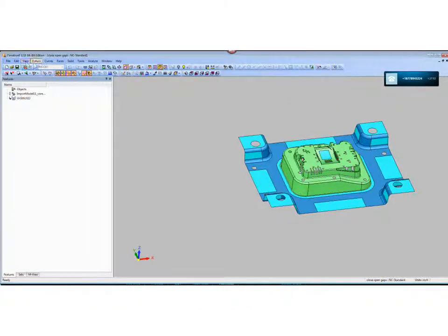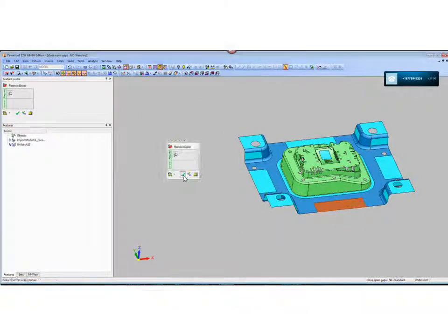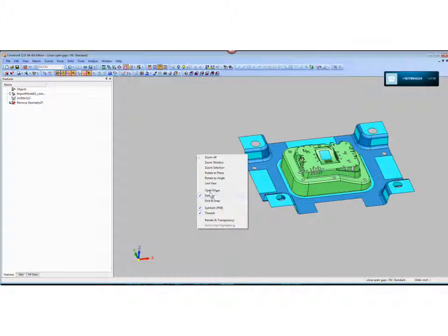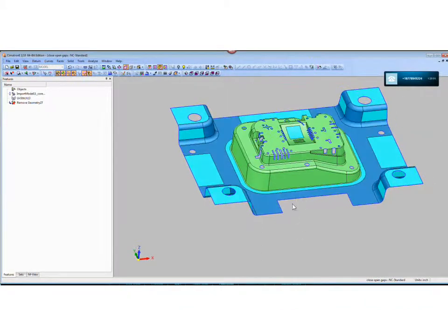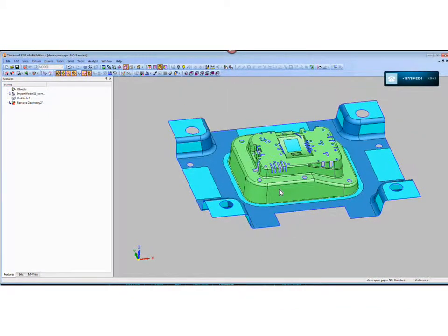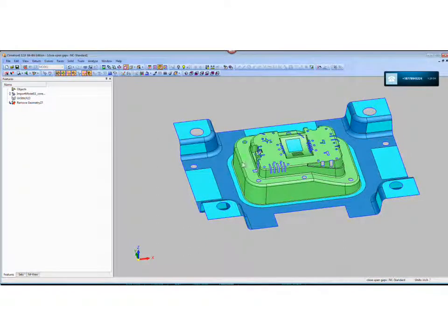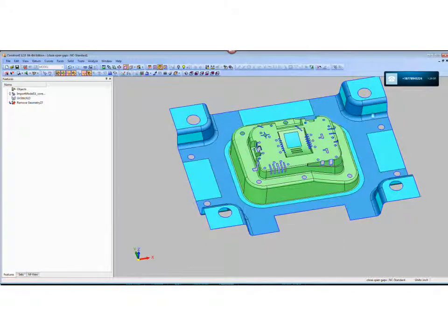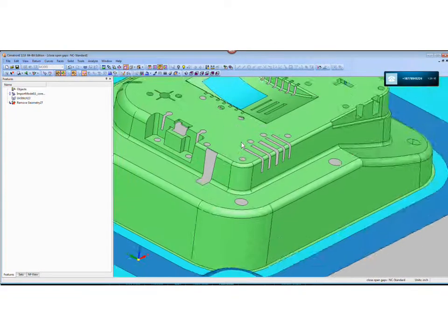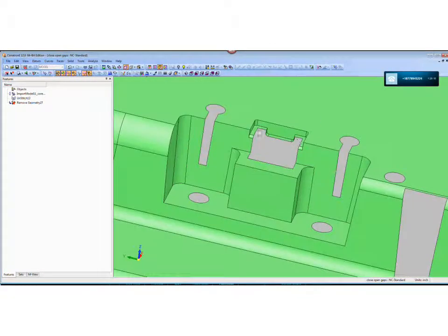And if I show you the open edges on my job, these are all open edges. In other words, this is not a closed, watertight, solid model. It's just a bunch of surfaces that are stitched together. And even so, in fact, let me just point this one out real quick. This one, if I want to put a patch on, wouldn't just be a matter of doing a chain around there and making a flat surface. There's a little bit to be done here.